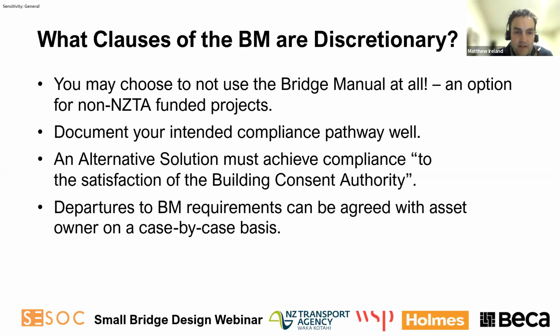Also, as Nigel indicated before, more often than not, bridges, even if they're designed to the bridge manual, won't meet all the requirements of the bridge manual. This is often covered in a departure process where essentially you're agreeing with the asset owner that you won't meet particular clauses of the bridge manual. This might be because some clauses are just not suitable for the context of the project or the bridge, or they might just be a bit too onerous.